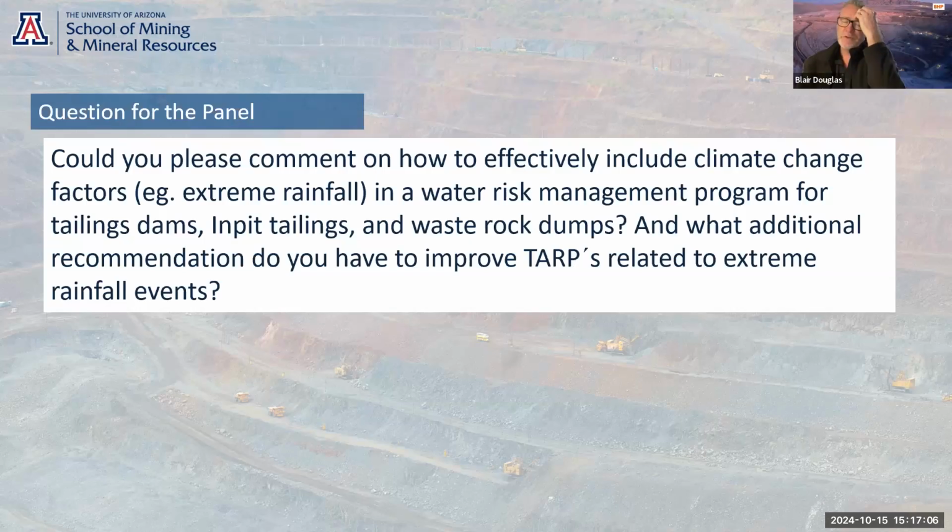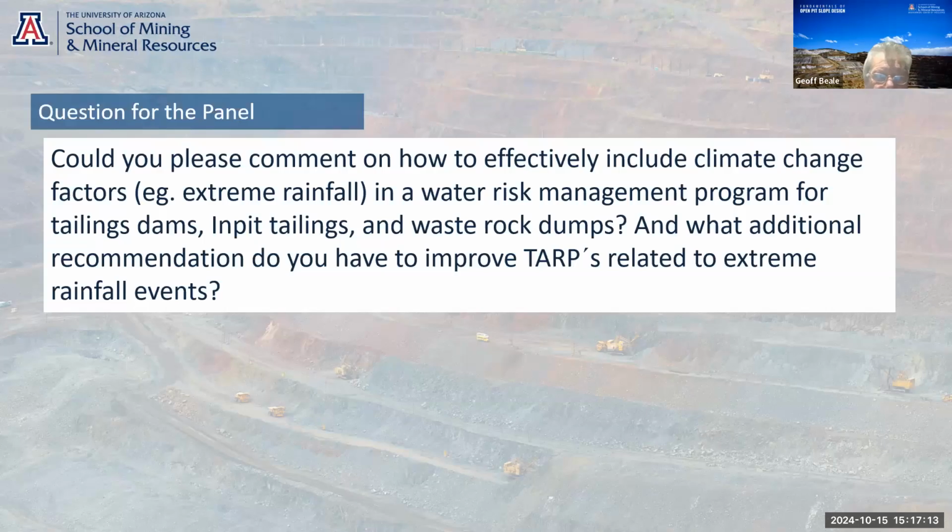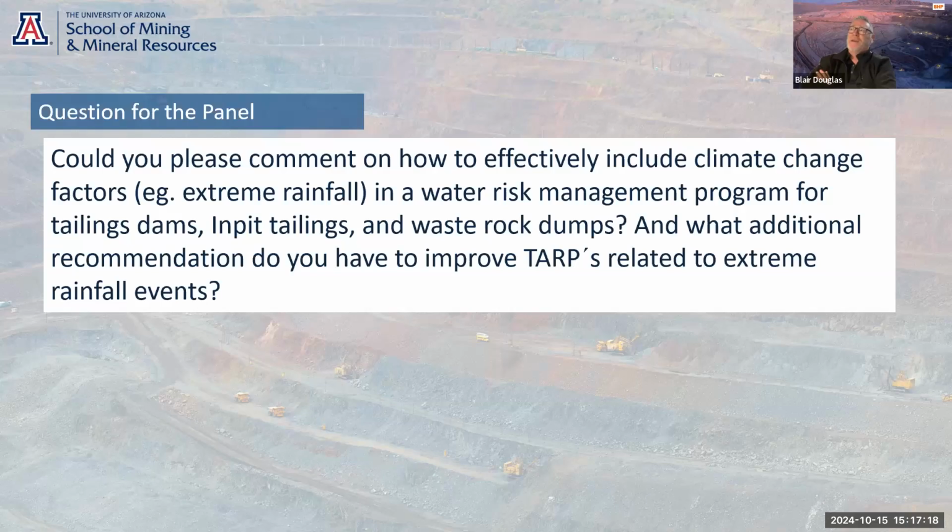Well, GISTM, the global standard for tailings in particular, sets out some guidelines on this. Depending on what stage of development you're at, it could be a 1 in 10,000 year event or a PMP. Putting a climate change factor around those numbers is enormously difficult. It increases cost significantly, but it's industry standard at the moment to close the site. I think for a tailings facility in particular, it's a 1 in 10,000 year event. Correct me if I'm wrong, which is enormous if you've got a spillway that you've got to design.